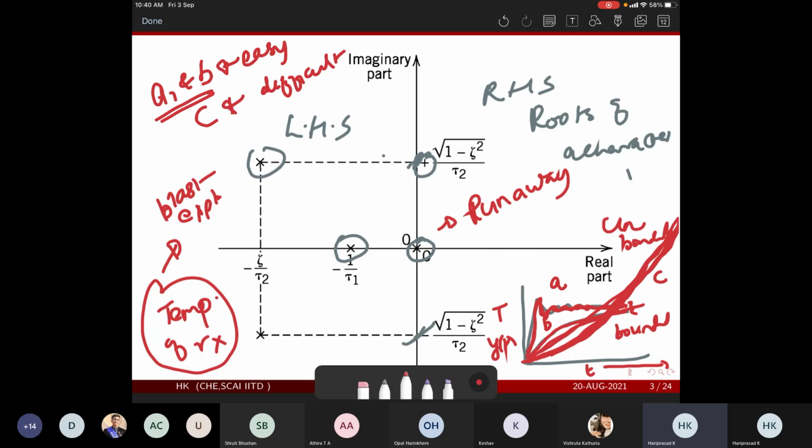To understand the overall characteristic, you need to look at the roots of the characteristic equation. The roots would give you an idea of the overall dynamics of the system, and as a designer, by looking at the position of the roots, you should design a controller in such a way that if the natural dynamics is to become unstable, you make it stable. So this is after adding the controller. The controller would suppress its natural instinct to go wild and give normal operation. This would be our ultimate aim.